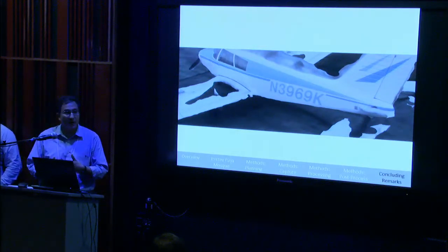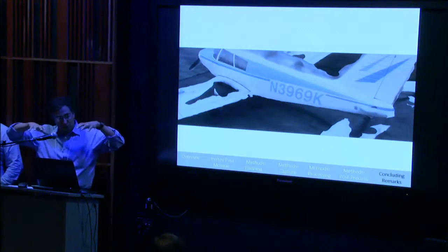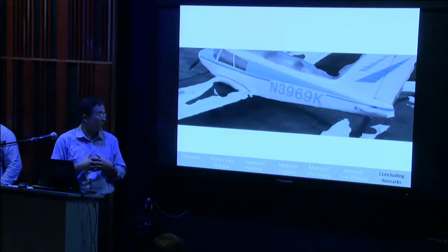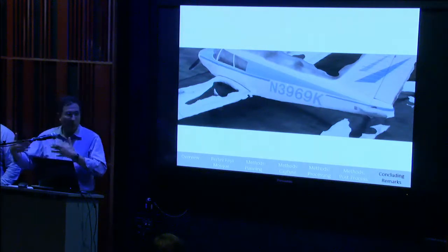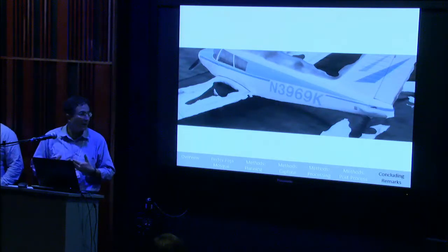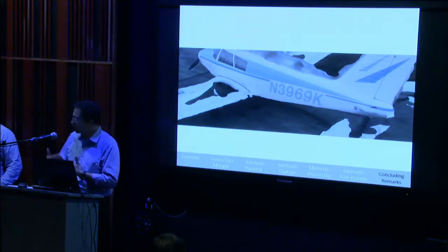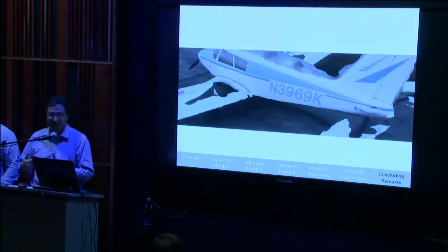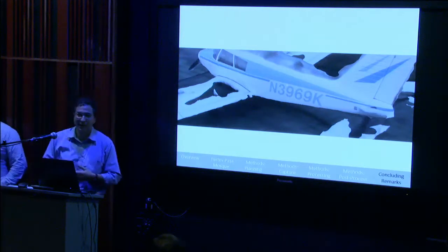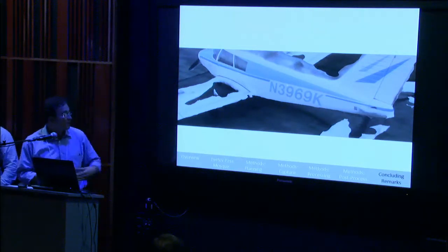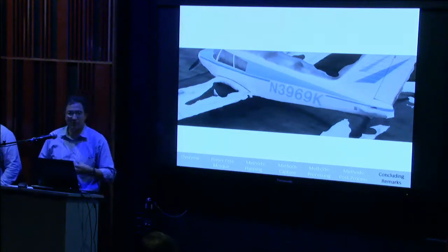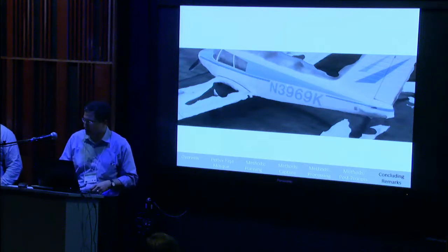So in the mosque, where you had very similar squinches and quarter domes, the fact that the calligraphy was unique was critical to the success of this project. But where you have long white walls or long surfaces that don't have a lot of detail, it becomes more difficult. One of the solutions Chris has come up with is different colored Post-it notes, putting them in several places to try to distinguish them. But what ends up happening is you get holes and voids where the software hasn't been able to process this.